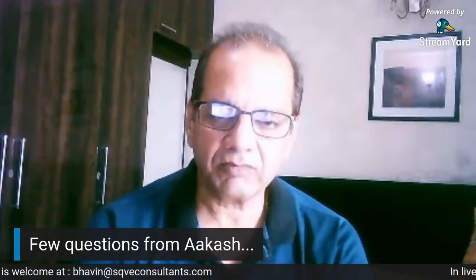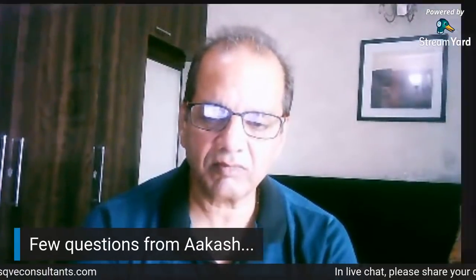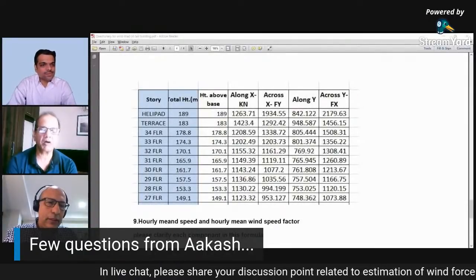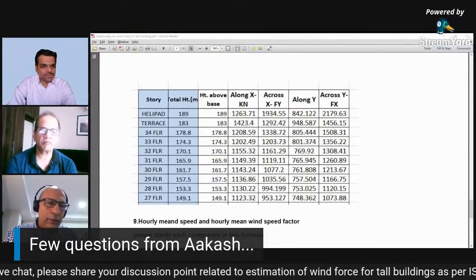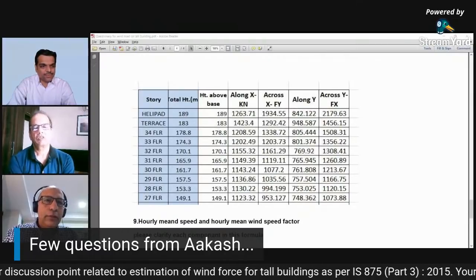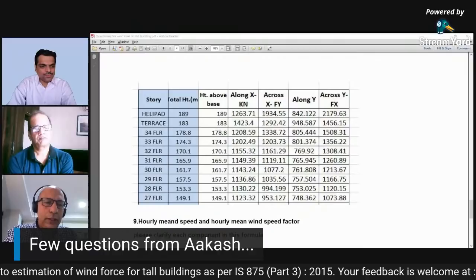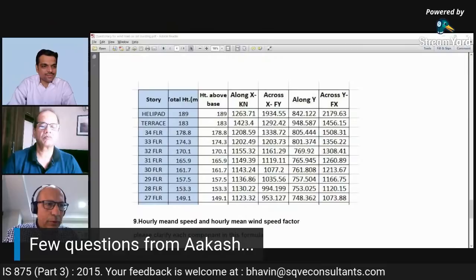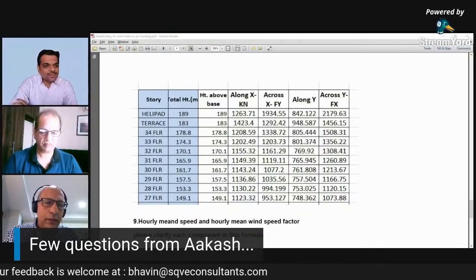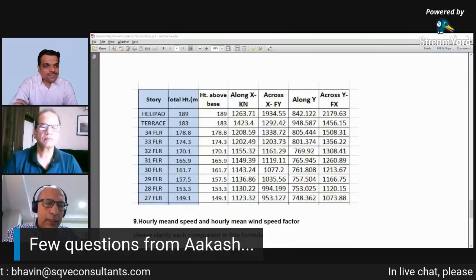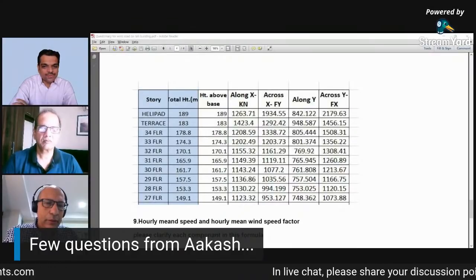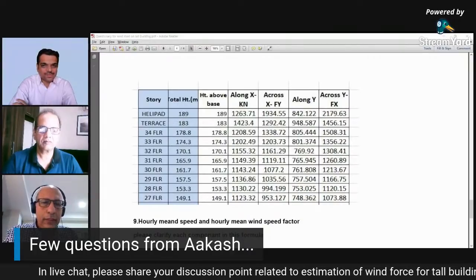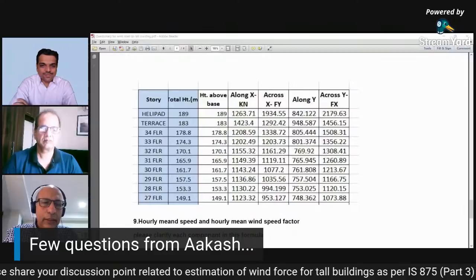Yep. Now there's a new version of the crosswind force coefficients. There's going to be an update in the next edition, which will hopefully come out before end of this year for the Australian standard, and this is based on the work of WindTech consultants. We've looked at a lot of crosswind spectra from numerous past studies that we've done around the world, some in India, of course, and we've derived from these a revised set of curves.